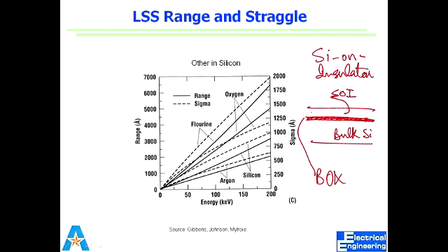They're just silicon wafers. What's the difference between this and growing an epi layer? You can't do it on top of silicon. For epi, you need a crystalline layer below to grow it. You can probably do it, but this is much simpler than epitaxy. Implantation is much simpler.